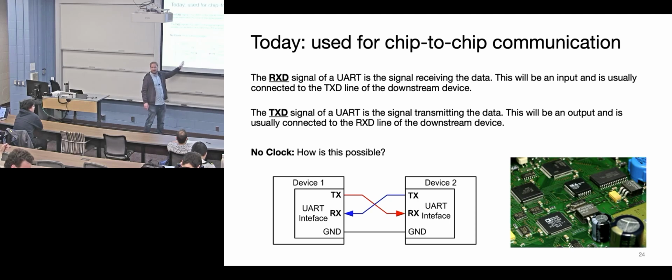They both have the same clock. They're oversampling. Imagine you have 1 clock that's going, say, 16 times faster. When it sends out bits, it sends out a 16th of that clock, and when the receiver resamples, it tries to figure out when the data packet came in. So these clocks are always going faster than your transmission back and forth, and that's how you can make up for not having a clock.